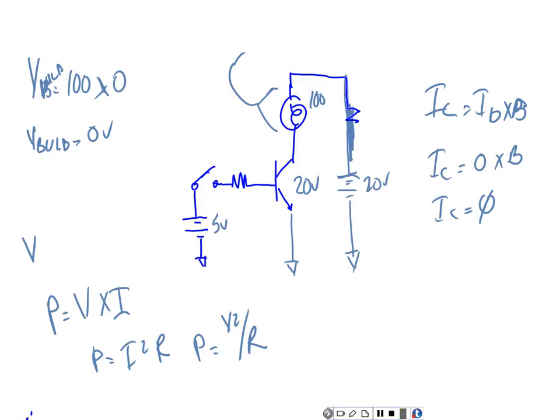125 volts at that current. So that means I can't go down to Radio Shack and buy this little old tiny switch that's rated at 12 volts and try to control a 115 volt circuit because it's not guaranteed to break, right? You understand that? Because that voltage is trying to do what through that switch? It's trying to push that current all the time.